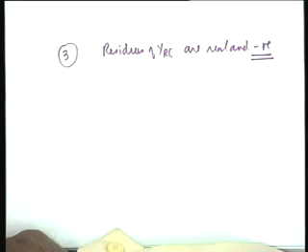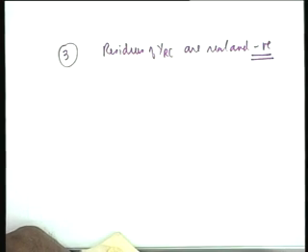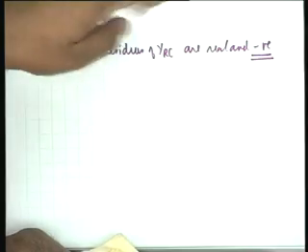Now, because they are negative, they are useless for us. We can't utilize them, all right. Because they are negative, we cannot use that partial fraction expansion. So, it also follows that if you wish to synthesize a given YRC in Foster 1 form, then you have to first divide by S and then expand in partial fraction. You understand what I mean?